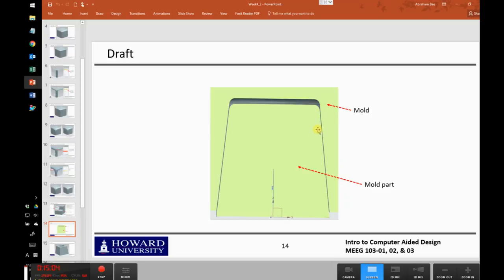When you do any molding for product manufacturing, this draft is a very useful tool because to do molding, there should be draft in the mold, and that draft angle will be applied to the molded part, and that makes it easier when you demold or take out the molded part, because that reduces the friction at this surface.